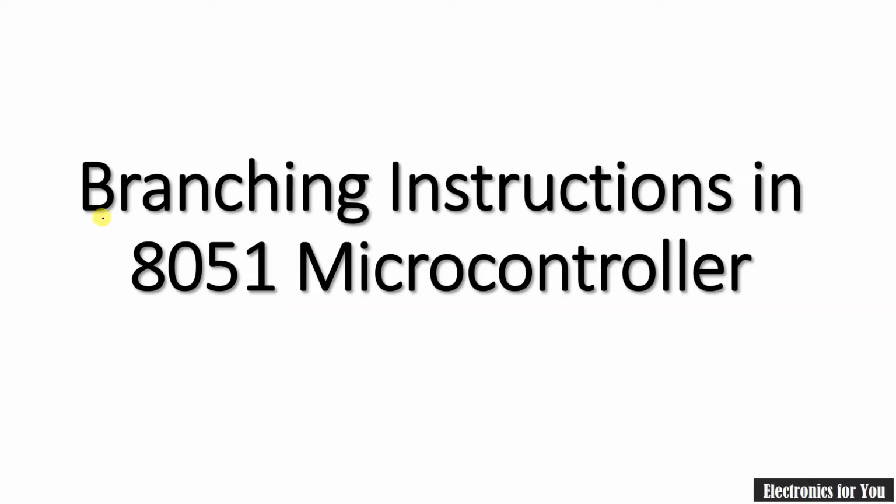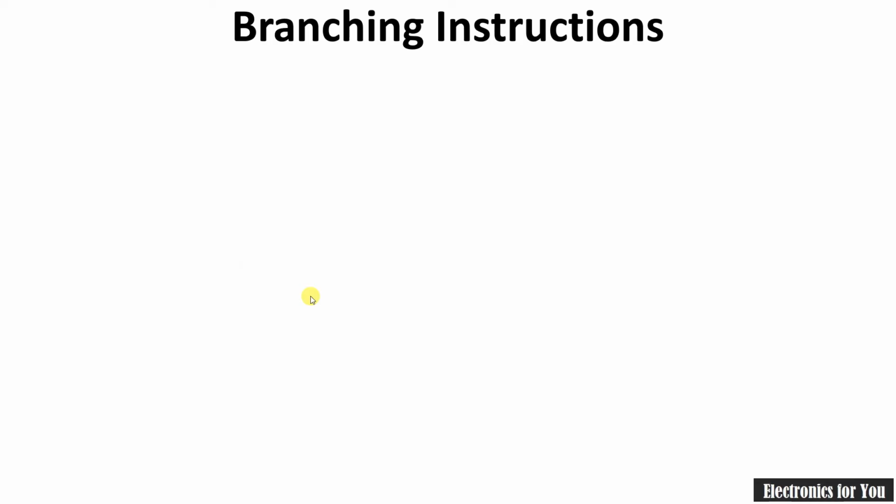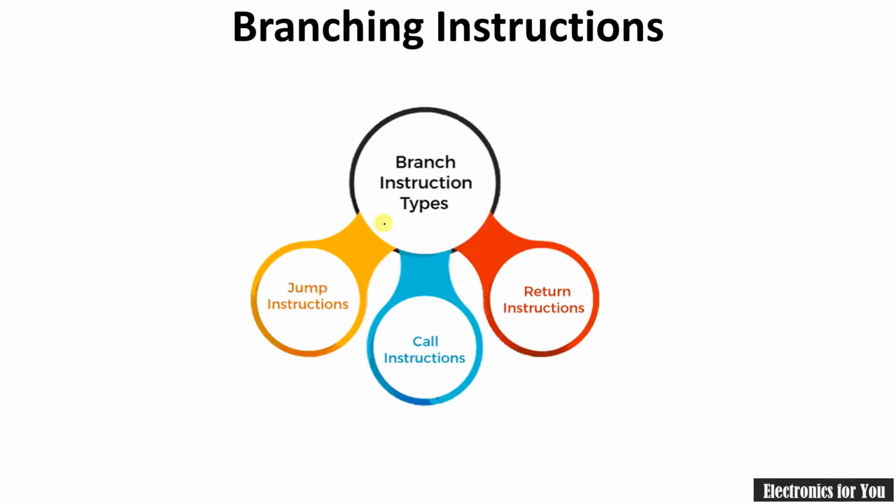In this video, I will explain branching instructions for 8051 microcontrollers. Branching instructions are classified into three main types: the first one is jump instructions, the second one is call instructions, and the last one is return instructions.